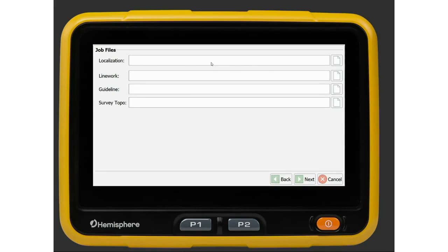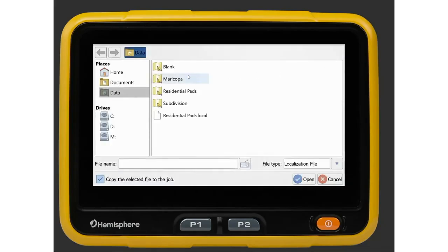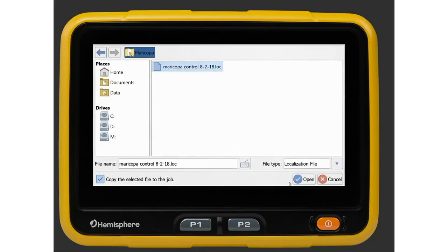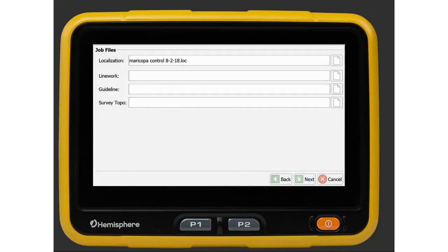When you get the control information, you will have to shoot each point using a rover. All this does is equate a specific lat long and height to a known northing, easting, and elevation. Once you complete this, you can save it to a thumb drive and bring it into Grade Metrics. We also have the capability to bring in a calibration file from Trimble Construction or export the point data needed from Topcon for customers with mixed fleets.